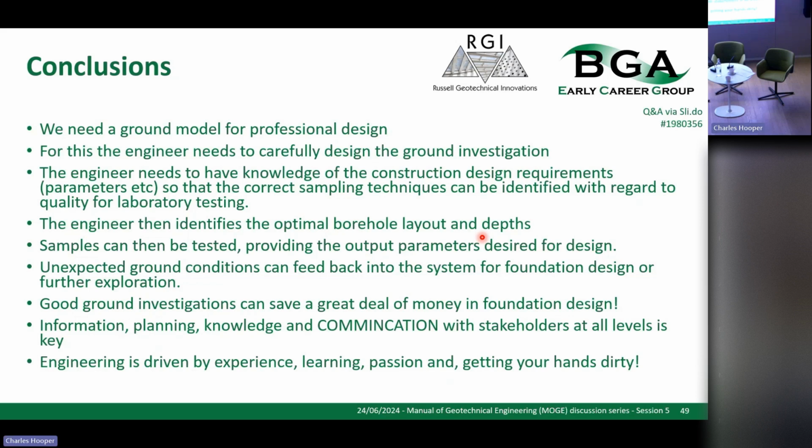In fact, just quickly, the test for silt: wet your hands a little bit, rub clay, and if it goes white within 30 seconds, you've either got a pure silt or it's a very silty clay. If it retains its colour, it's clay. So, okay.